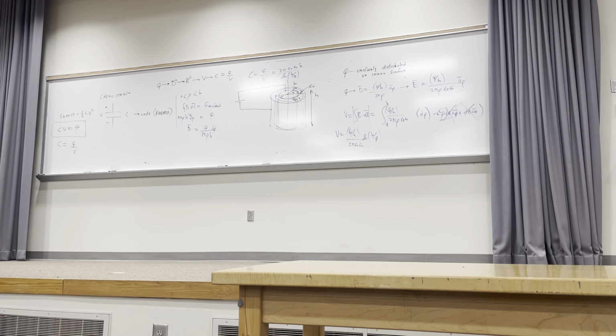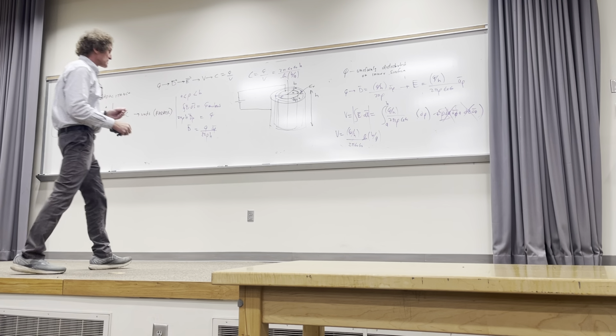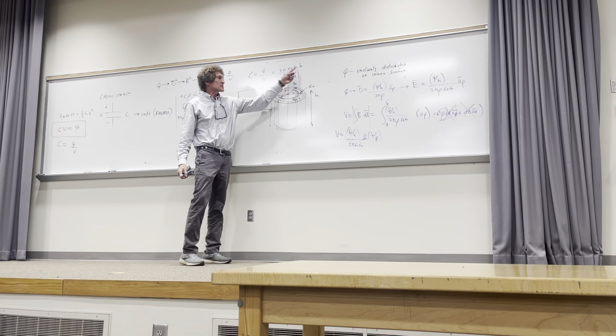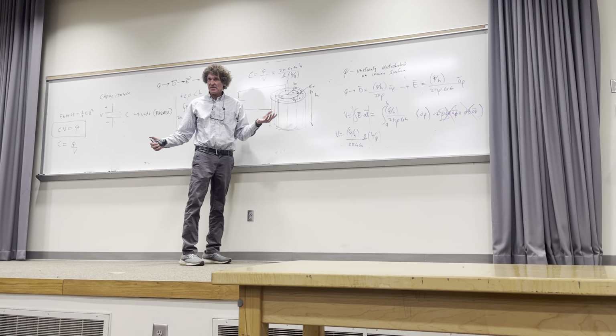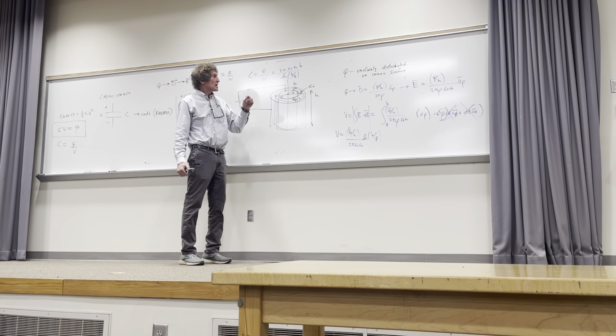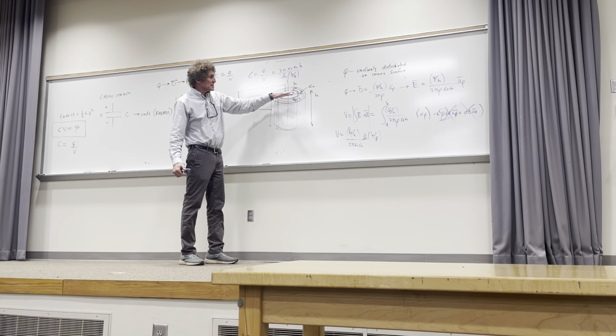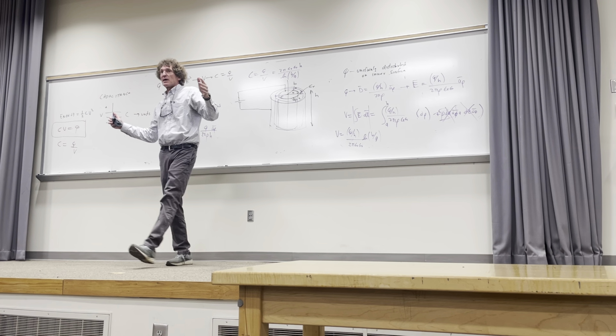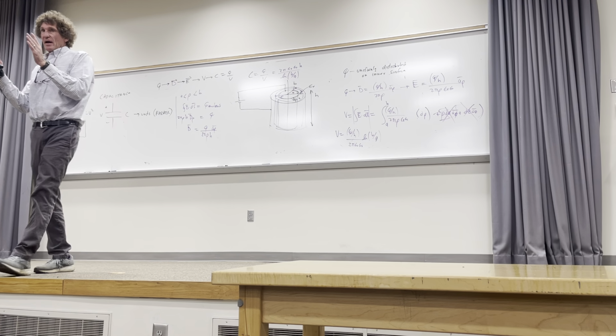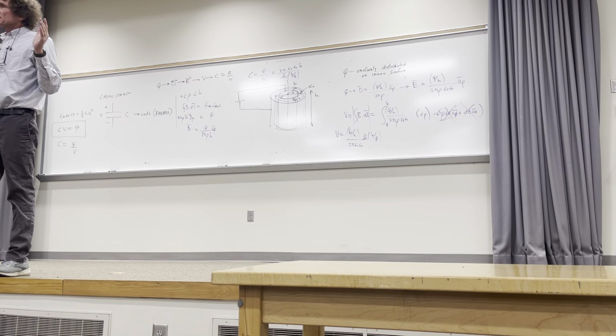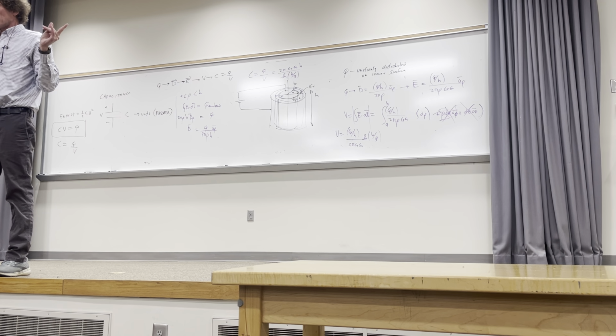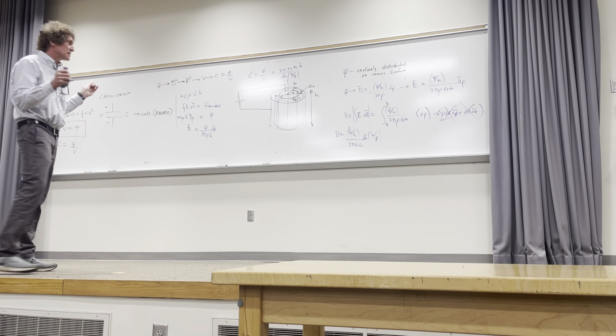Now, this one, take a look at, and try to glean this from this. Try to just make sure you appreciate it. Again, it checks the box. It's proportional to epsilon. It has to be directly proportional to epsilon. If it's not, you've made a terrible error. It's also proportional to the length. The longer that is, think of parallel capacitors. If you have H and I double H, what I've basically done is put another capacitor in parallel. It is exactly proportional to H. Y'all follow me on that? It checks that box, sanity check.